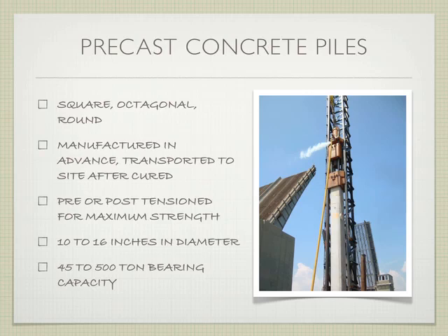Yes? The salt doesn't affect the steel rebar inside? Great question. We will talk about this when we get to reinforcing anyway, but if we were going to put this in an environment where they could potentially be in contact with salt water, we would use one of two things. One, we'd use stainless steel rebar, which is resistant naturally by its process of being made, or we'd use epoxy coated. We wouldn't use zinc because it reacts with the concrete, but we'd use epoxy coated.